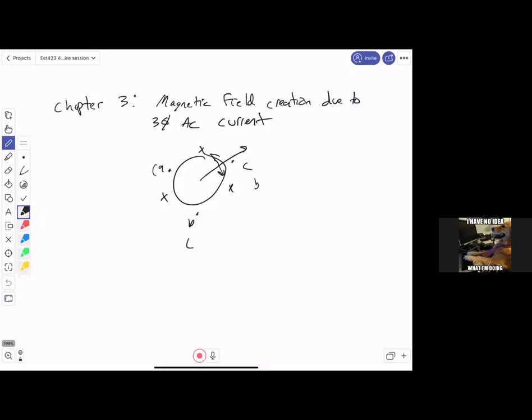So all I know is that I have A, C, B here, right? And I can just move these around. These windings that I see here are nothing more than a set of windings. I actually don't have to call them A and B and C that's circled. I can connect those any way I want. If you're an electrician in the field, you've got 3 leads coming out of a motor.